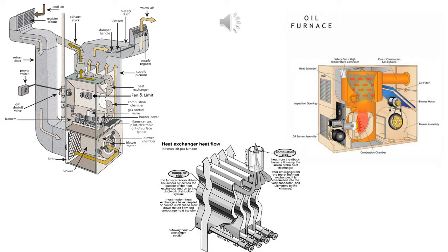Now that you know how to distinguish between the different furnace designs, we will cover the basic parts of a furnace. We will start with combustion chambers. On a gas furnace, the combustion chamber is smaller than on an oil-fired furnace. An oil-fired appliance needs a larger chamber to properly burn the oil. I am not going to explain it further than that because it is beyond the scope of this class. The heat producer is the manifold on a gas appliance and the burner on an oil-fired appliance.